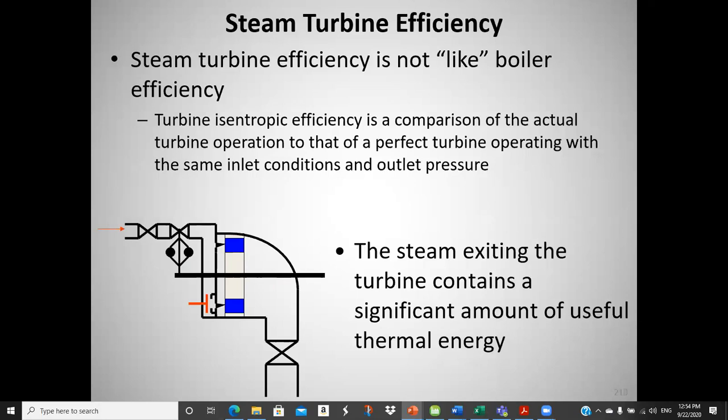So on a pump, you put the isentropic pump work on top and divide it by the work into the real pump, because you want that to be less than 1. So if it's consuming work, you want the ideal on top and divide by the real. If it's producing work, then you want to switch that, like the turbine, because the ideal turbine is going to produce more work than the actual turbine. So you got to swap those things. And once you understand the concept, you don't even have to write down the equations, because it's usually just the enthalpy difference across them. So it's pretty simple.